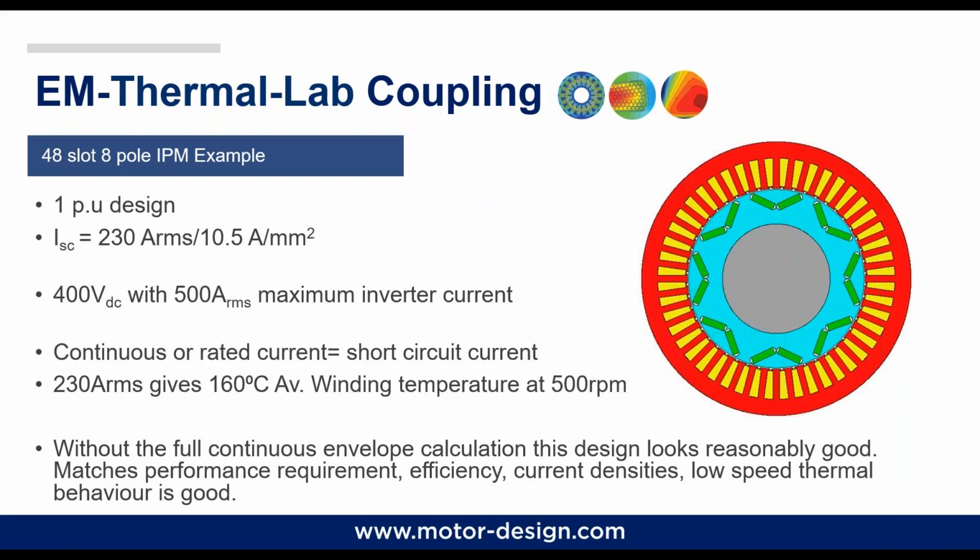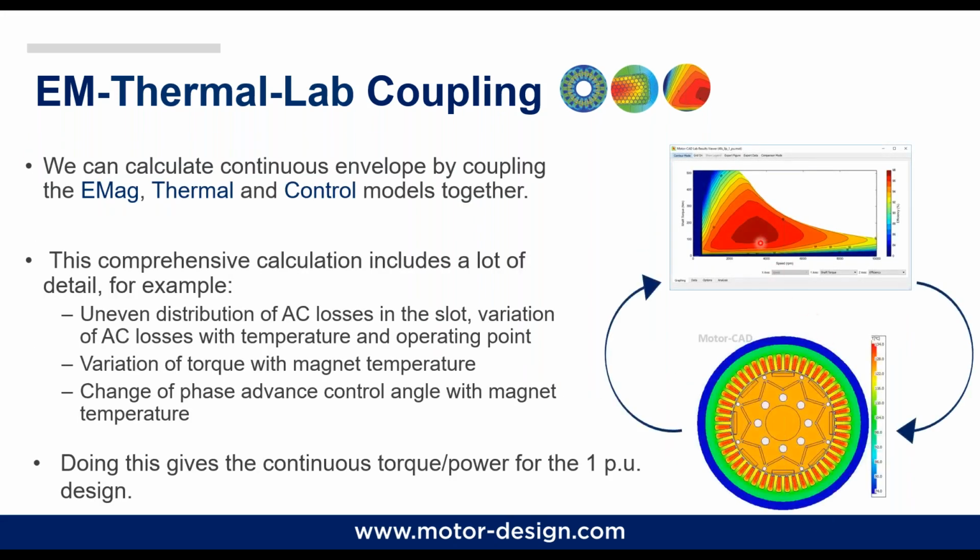First of all, we need to get the losses inside the machine. So we build the so-called efficiency map, and then we calculate the operating points in which the machine is going to operate over the drive cycle. After we get our losses, we automatically link them inside MotorCAD to the thermal module, and so we can run our lumped circuit parameter network, the one I was showing you before, and understand the temperatures in each part of the machine during the drive cycle.